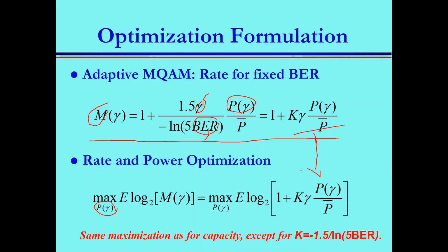The receiver receives the signal from the transmitter. Yes, then the receiver measures the average SNR and does some calculation, and after all these calculations, he finds out that the best modulation that maps to this signal to noise ratio is this. This modulation corresponds to number 3. Then the receiver sends back number 3 to the transmitter, telling him please use mode 3 for transmission because this is my condition, this is my situation. So the receiver keeps updating the transmitter every once in a while to make sure that both of them are utilizing their transmission efficiently.